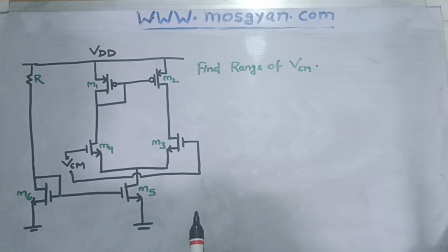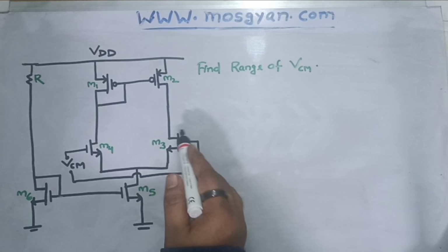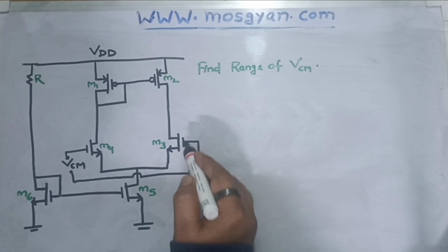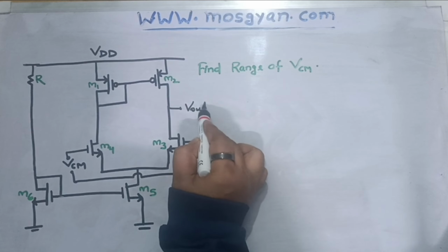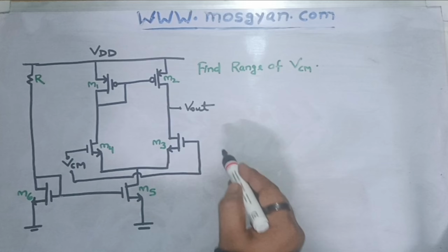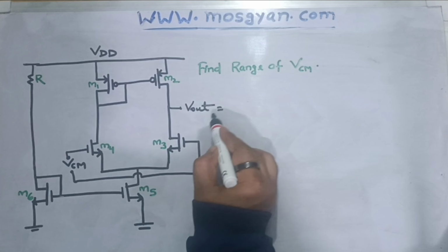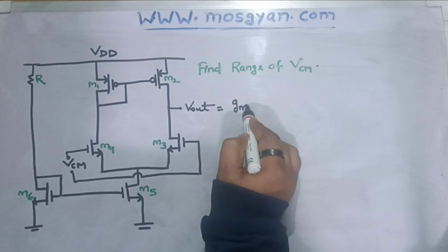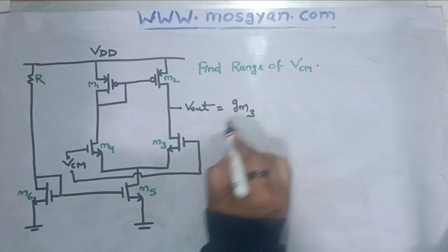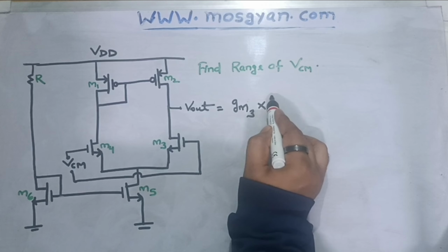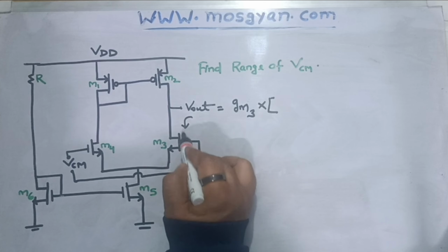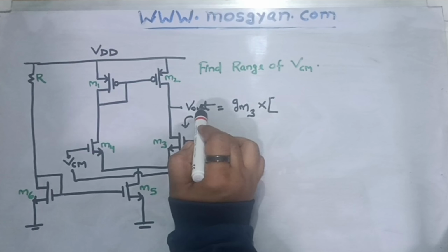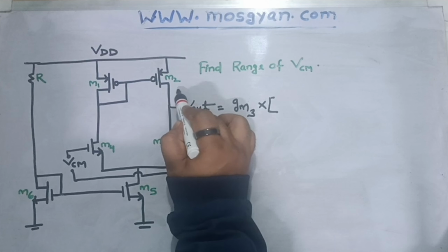So we know for any such kind of structure, if we have to calculate the gain of this op-amp, let's say we are taking a single-ended output from this end, which is denoted as V out, and if I have to write the gain expression, so in general we write GM, transconductance of this input MOS, let's say GM3, which would get multiplied with R0, which will be the resistance seen from this node downwards and resistance seen from this node upwards, parallel combination of that.